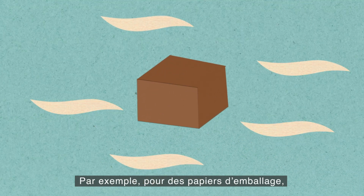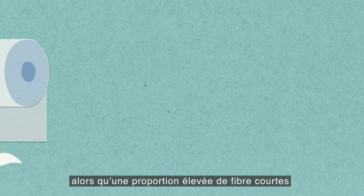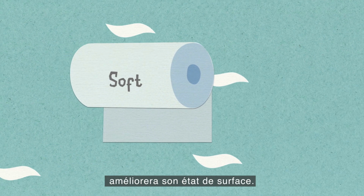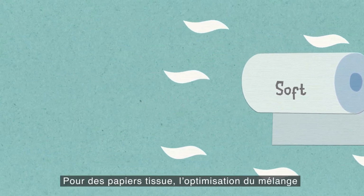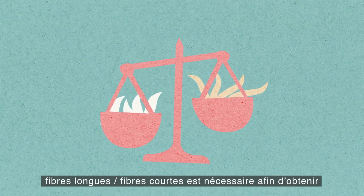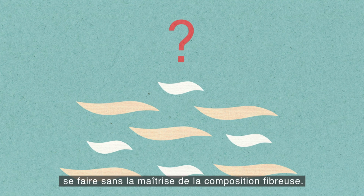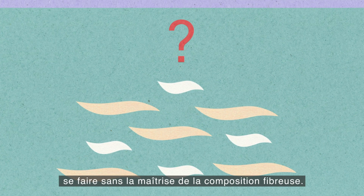For instance, in packaging, a high portion of long fibers will create a stronger sheet, while higher portion of short fibers will give better softness. In tissue, optimizing the blend of long and short fibers is required to achieve desired strength and smoothness. If you don't know your fiber mix, you cannot control the final output.